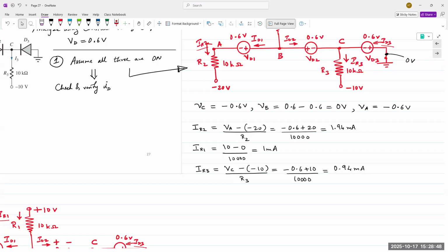So from these three, how can we go about finding the diode currents? What techniques come to mind? KVL, yes, but we have currents. KCL. So all of circuit analysis is just based on three, right? You've heard me state this before, perhaps. Ohm's law, KVL, KCL. Everything else is derived from these three techniques. If we wish to find voltage, think of KVL first. If we want to find current, think of KCL. And for everything else, of course, there's Ohm's law. So how would you go about finding the diode currents?